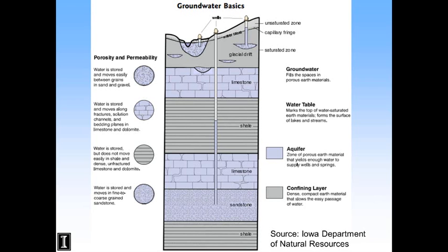And if I haven't mentioned it, an aquifer is the geologic unit that will yield enough water to a well, and an aquitard, or a confining layer, is a geologic unit that, even though it may have water in it, doesn't allow water to flow readily to a well when you pump it. Those usually limit flow, versus an aquifer that allows flow to a well.